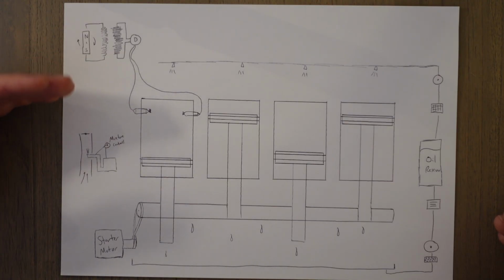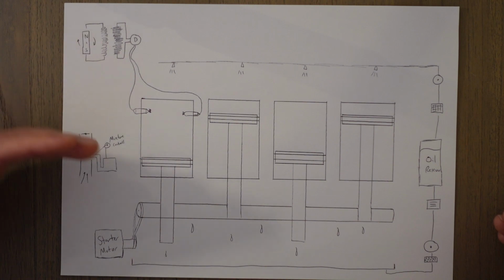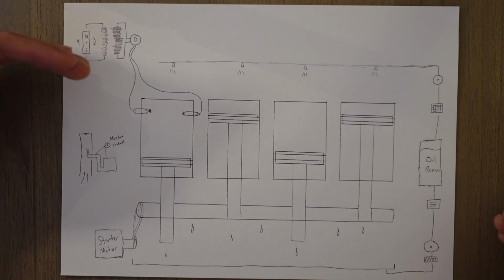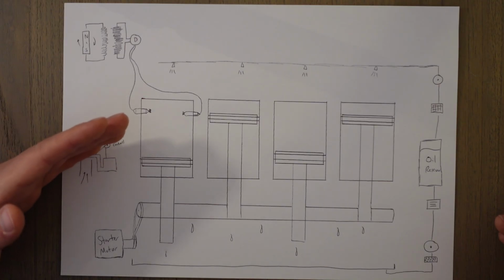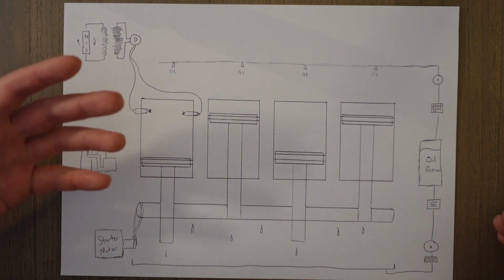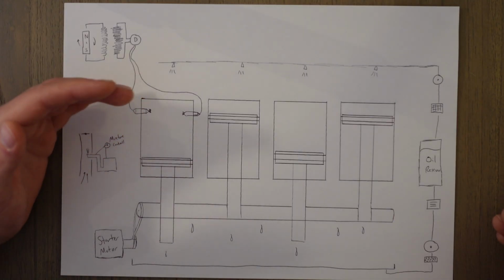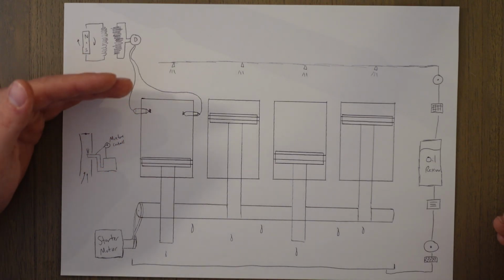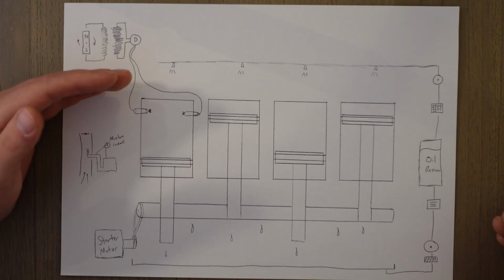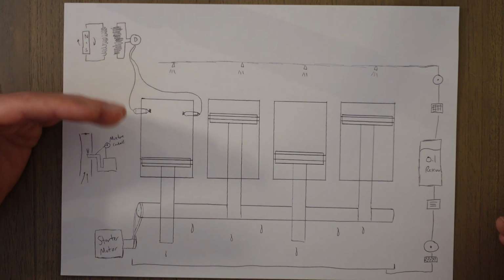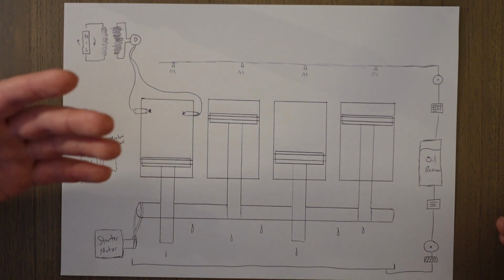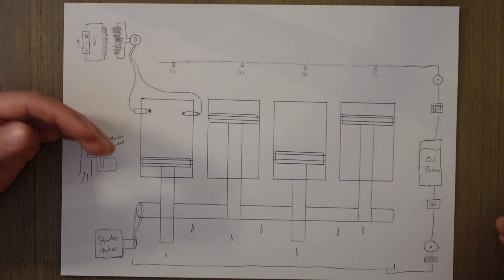This will delay the effects of reducing power with altitude, either by ground boosting, which is basically giving us more power to start with, which causes the reduction to be less drastic with altitude, or you can tune it so that it provides just the right amount of boost at a set altitude, RPM, temperature, etc., and that way you get the most fuel effective and best combustion at a certain altitude, therefore giving you way more power at that altitude. And if you don't need that power, you can operate the engine at 80% of its normal full capacity, and that means that it's good for fuel efficiency, engine wear and tear, etc.